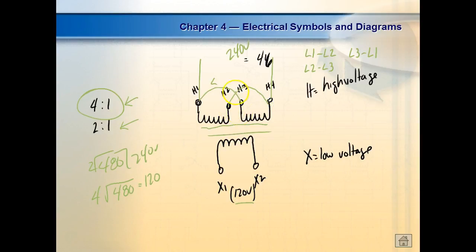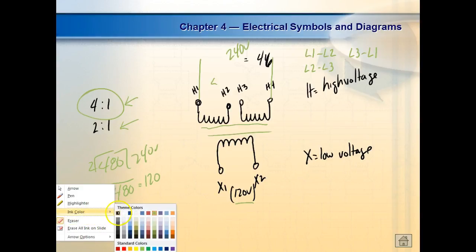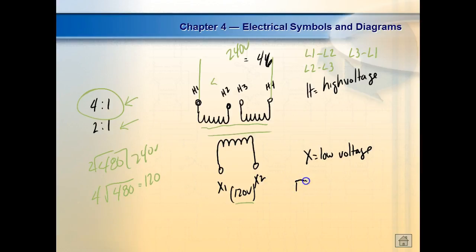Now look, what I just did is I did what? Cross wires. So what they did a long time ago, so you can check this out really, really fast, is they deliberately, on the diagram, cross these wires right here. And this is the way the transformer's wired. So if you look at the actual lugs on the transformer, it went H1, and then the next was what? H3, and the next one was what? H2, and then H4. And I'll show you why they did it like that.